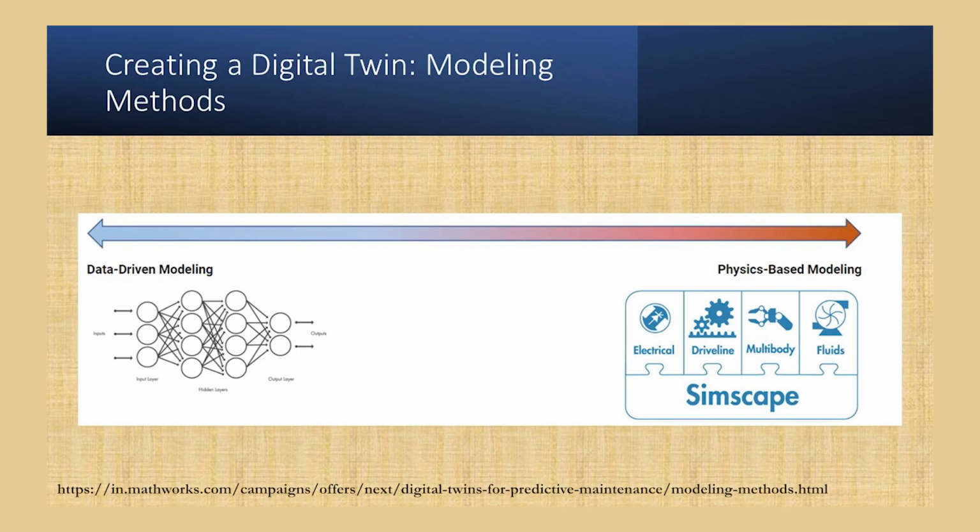This model is updated with time based on the outputs that you are seeing for various input levels. So, it is based on data. There is no analytical model, there is no equation that is giving you the material removal rate based on the input parameters. It is just a model which is based on neurons. So, that is known as data driven modeling.